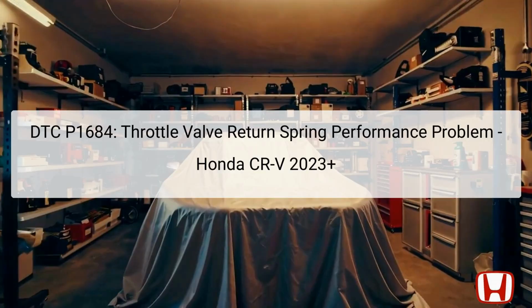The error code P1684 indicates a problem with the throttle valve return spring performance in the 2023 Plus Honda CR-V. This issue arises when the throttle valve fails to return to its target position after being actuated. The Powertrain Control Module, PCM, detects this abnormality and subsequently stores the DTC. Components affected by this issue include the throttle body and its associated spring mechanism.